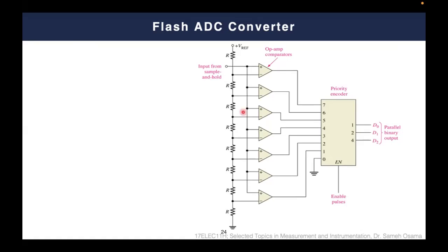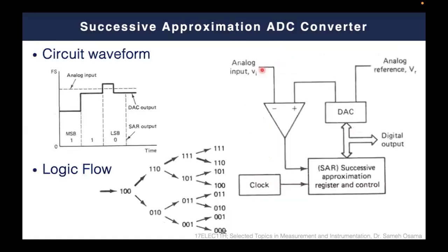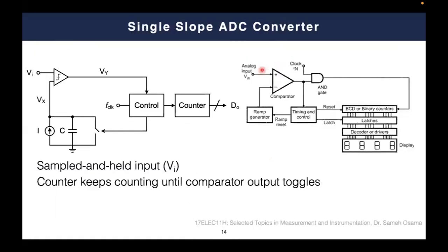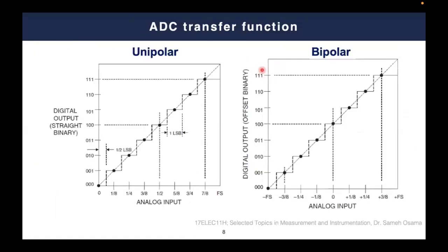And simply, we are here relying on 7 comparators. And the idea here is simply consistent with what you see here. As you can see, we have a variation between 8 states. If you are from 0 to 1/8, then you belong to the first state.